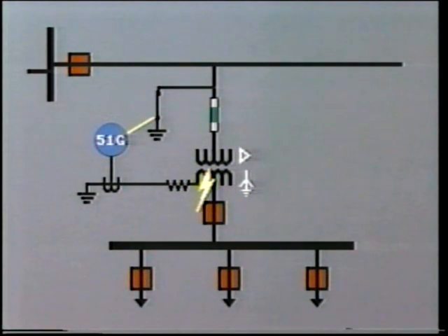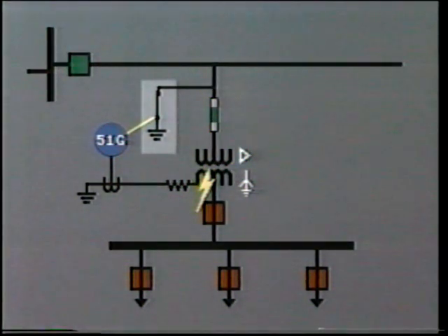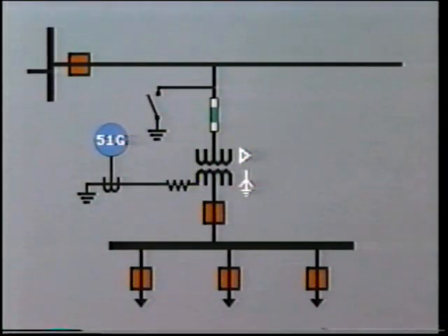This, in turn, causes operation of the ground relays in the remote station and so opens the breaker. Depending on system design, the ground switch could be three-phase or single-phase. Generally speaking, the ground switch arrangement is not often used on new installations.